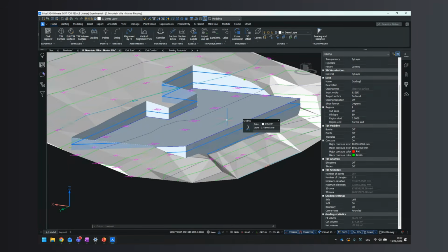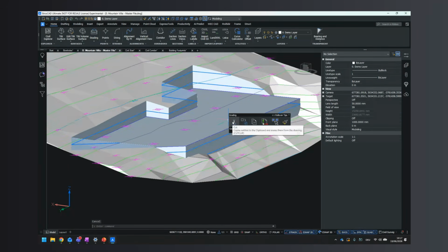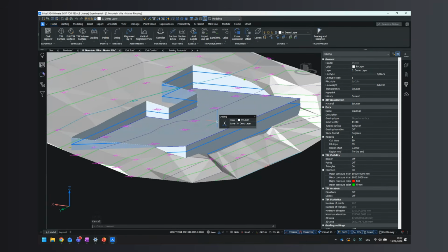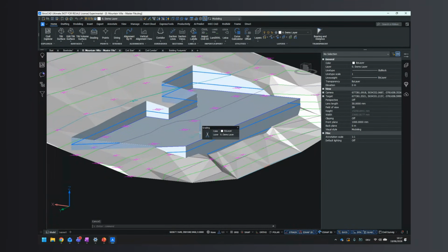But here is a small trick. If you want to find where your elevation should be, in order for the cut and fill volumes to be the same, so you don't need to bring trucks in and get rid of soil. There you go. Civil balance grading volumes. This is a very interesting tool that balances the gradings and finds where the new elevation should be in order for the net volumes to be 0.